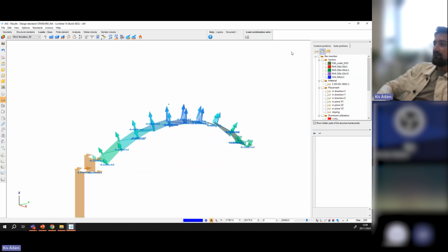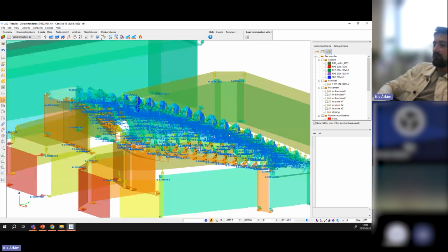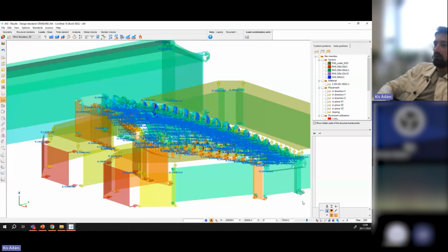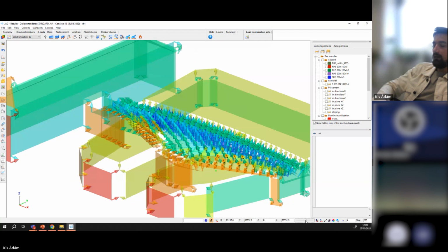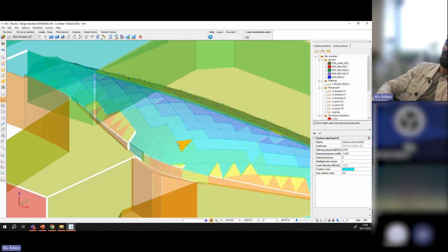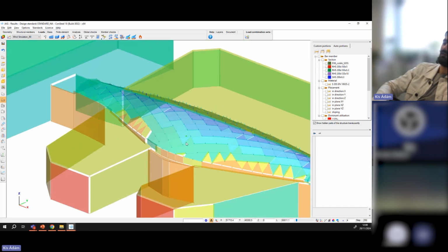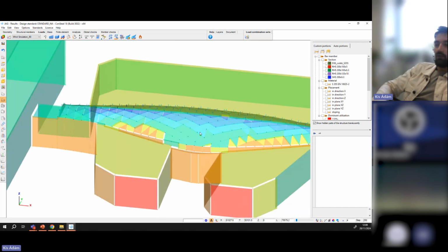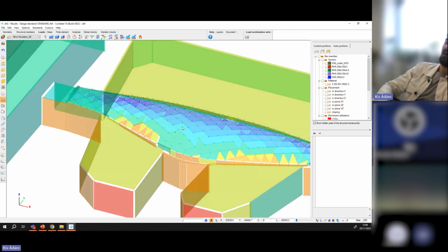Again, this is a scenario which contains multiple elements, which does not require additional meshing. So this is when for one simulation surface, there is only one surface wind load. So in this scenario, that tick, the flag with the meshing, does not have to be active.